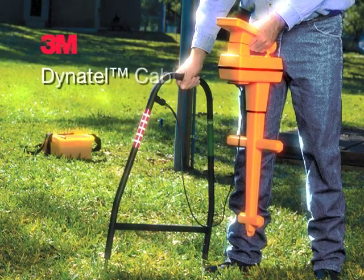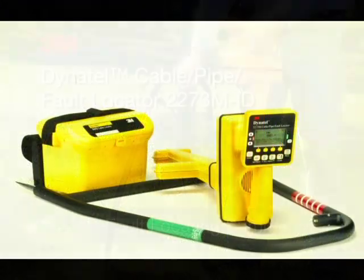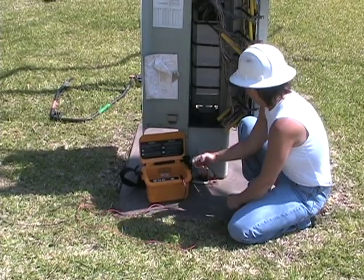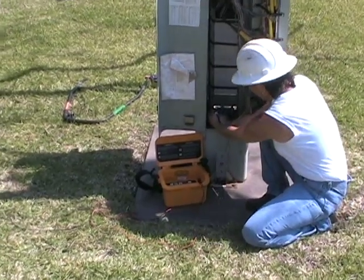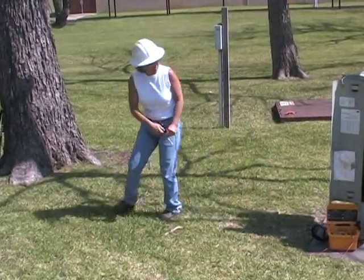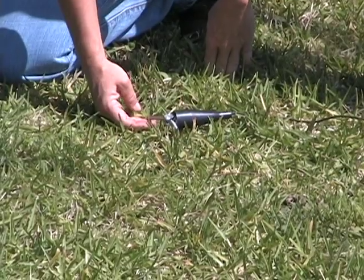This chapter will cover a quick review of fault locating with the 3M Dynatel 2273 MID. In order to pinpoint a fault, it is necessary to isolate the faulted section of the cable at both ends. Connect the red lead of the transmitter to the faulted conductor, and the black lead to the ground rod that you have placed in line with the suspected cable path.